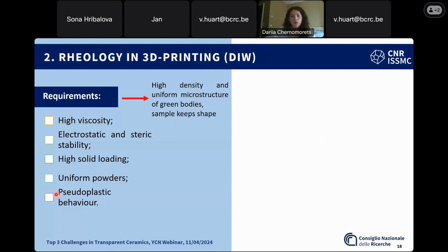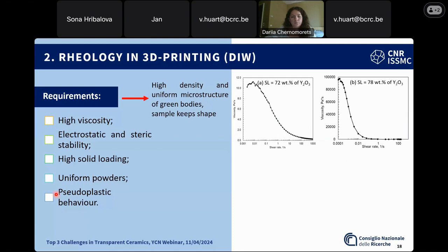On the other hand, with SPS, that's much more tricky, but it's also much more the issue, because what you usually do with SPS is you put in samples that don't have closed porosity. They're mostly powders, pressed compact, and so there, for a simple powder compact, that might become unavoidable.